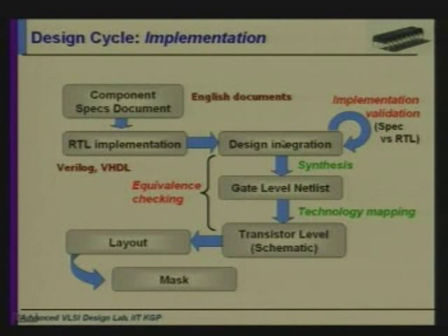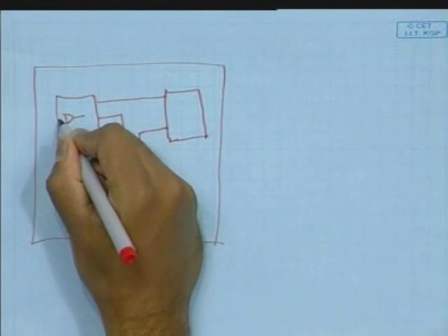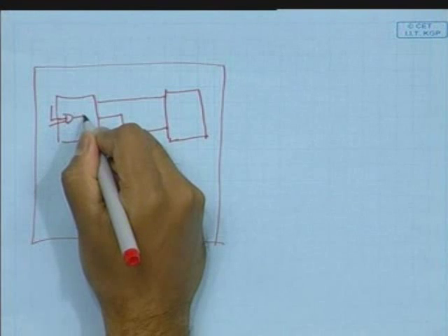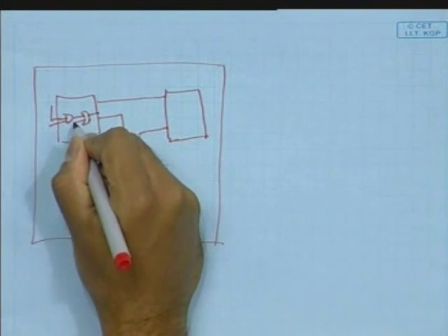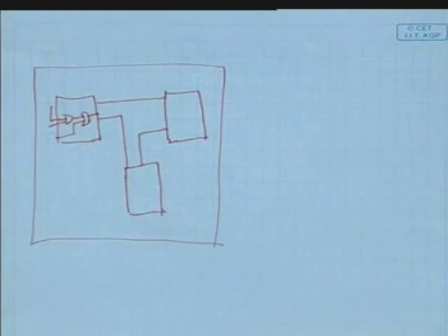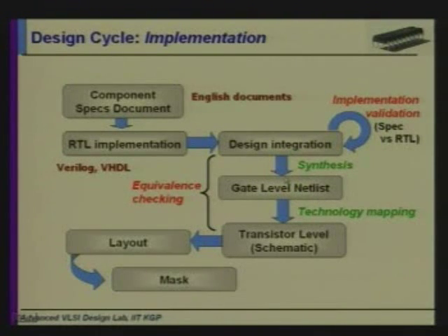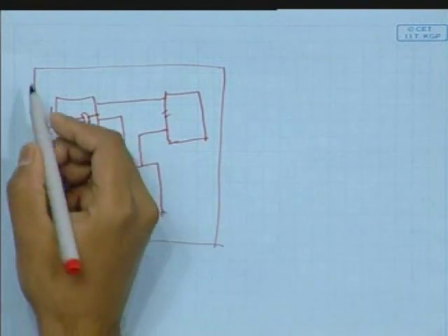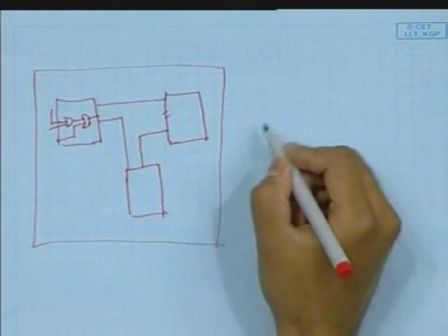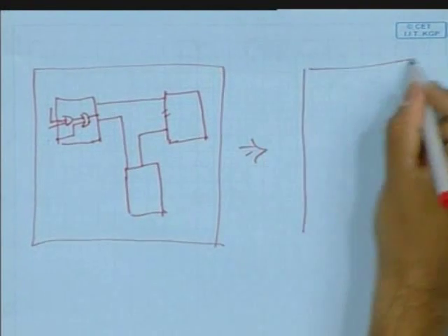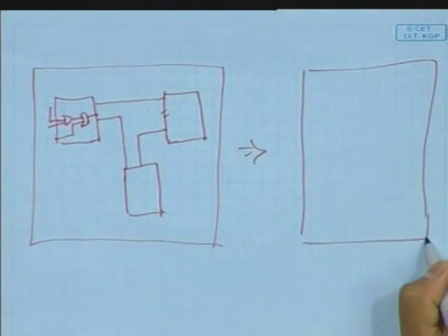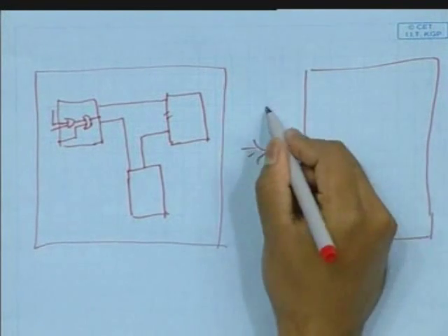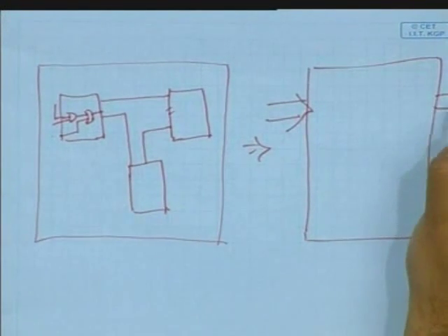Like if these are typical RTL level descriptions, after this we will have a gate level netlist with AND, OR or these kinds of gates. So after this we won't have these module level boundaries. Instead we will have an entire big flat module which consists of only gates, and we will have a set of inputs here and a set of outputs here.